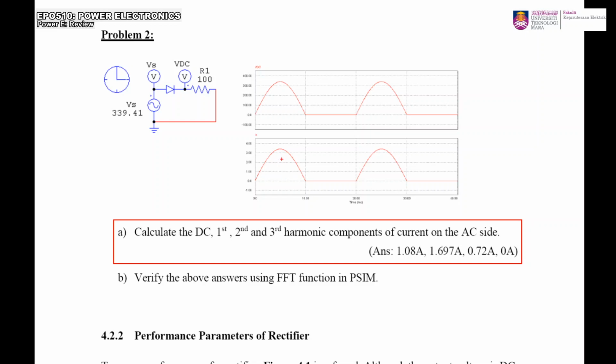So if you look at this waveform, I don't think it is an odd waveform. It is not an even waveform. It is not an odd waveform, and it also does not have half wave symmetry. So you have to perform as a normal function, an, bn, integrate. Inshallah, you will get this answer, right? Answers, and compare with your PSIM.